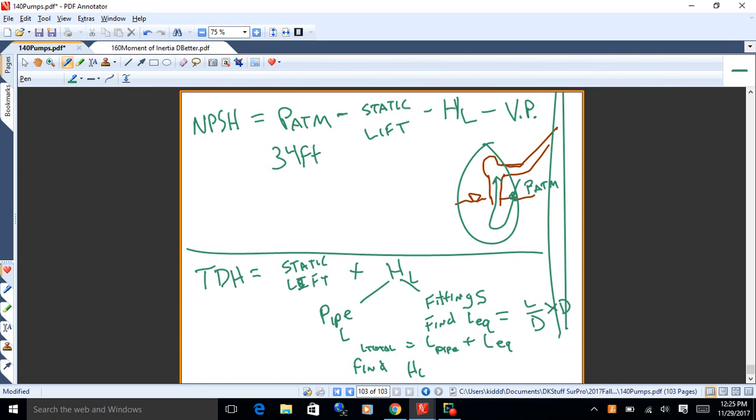All right, and then I'll also give you some horsepower calculations. And the horsepower is, again, lower right, GPM times head over 3960. That's all you got to do. Then you use the efficiency to get to the brake horsepower and the motor horsepower. Just remember to divide by the efficiency.